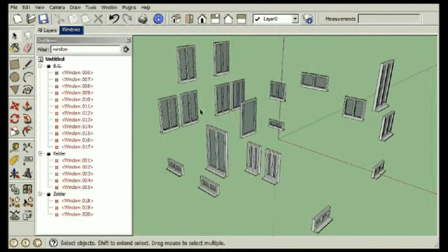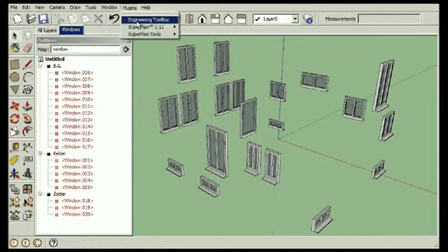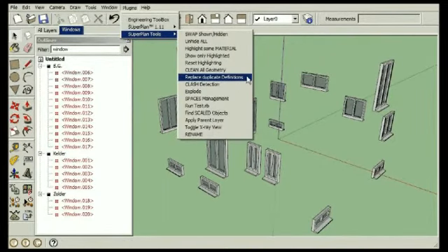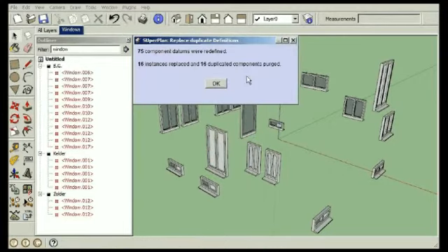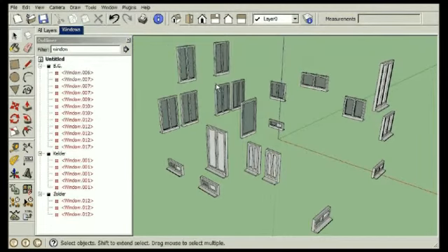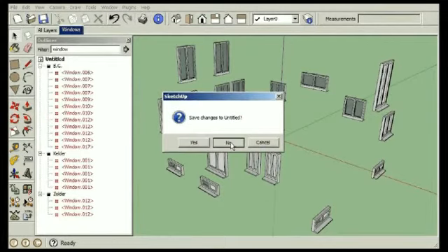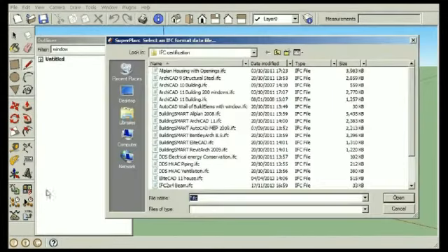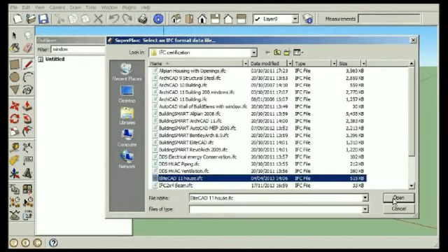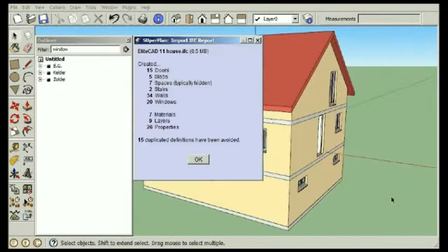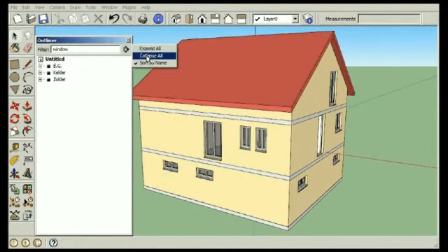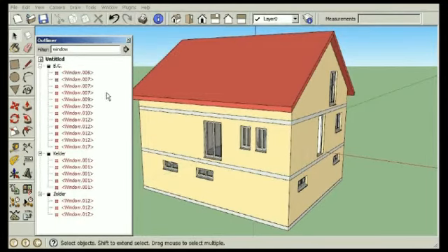Displaying just the windows, some appear to be identical. A SUperPlan tool can process the whole model to find and replace duplicate definitions. Not only will your bill of materials be improved, but your model size will be significantly less. Multiple definitions of the same component are commonly defined by BIM data, so the SUperPlan IFC importer can automatically detect and substitute duplication. However, sometimes the manual tool is still required.